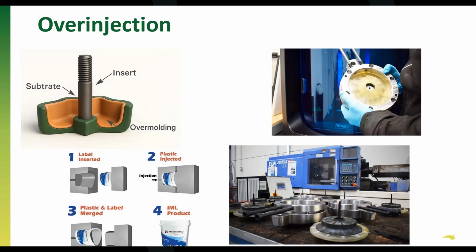Another case that we developed in our facilities is a hollow structure in which we 3D print a part separately, overinject it, and then remove this 3D printed part in order to obtain a hollow structure, which would be impossible to make only by injection molding. So the key in this case, and it's possible to do with fossil and bio-based materials, is to combine the different technologies or see how we can adapt everything. In the next slide.